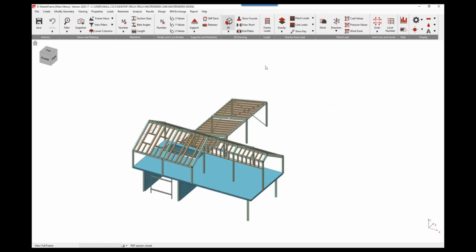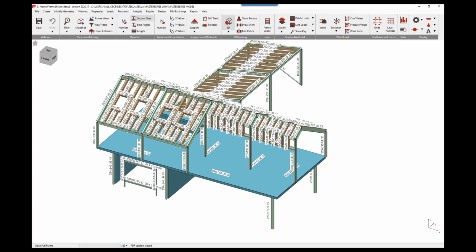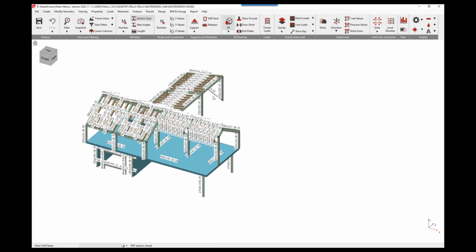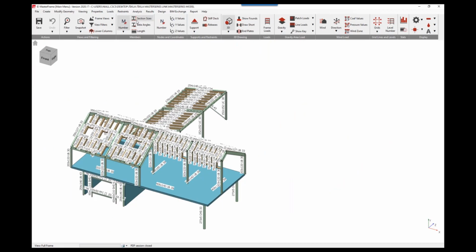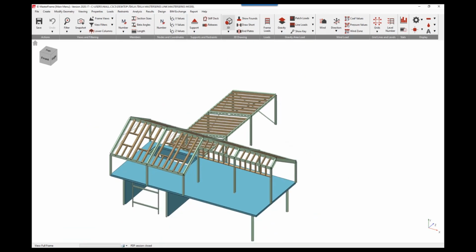Okay, so if I switch on 3D view, you can see that it's taken through the 3 different materials, concrete, steel and timber. And our steel sections have all the profiles that we expect to be applied from our CHSs, the UBs, the SHS, the twin PFC, and down the back we've also got our angles. You can also see that the members that have been decorated with the web openings have their circular openings and the rectangular opening, and that the FE slab has come through with the opening in it for the staircase.